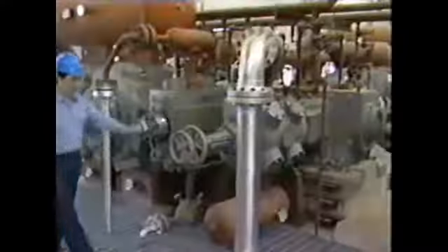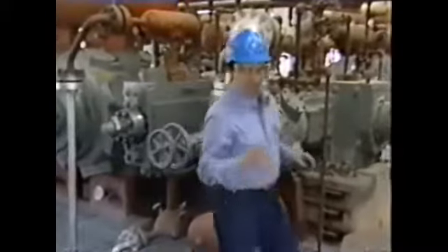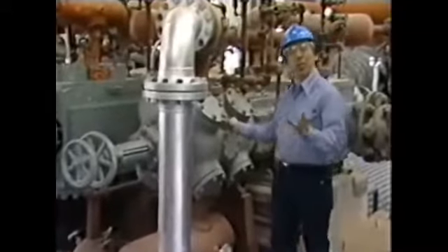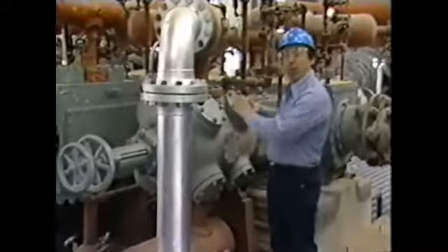Within the crank-end head is a set of metallic packing rings. These rings prevent gas leakage around the piston rod. As the piston reciprocates within the cylinder, friction caused by that movement will create wear within the cylinder. Because of this, most cylinders are fitted with a liner, and pistons are also fitted with rings. Now, by replacing only liner and rings, a cylinder may be repeatedly repaired without having to replace the entire compression unit.